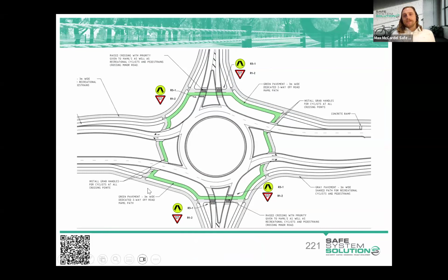So that's when we've got the single lane roundabouts. But when we're talking multi-lane, things get a bit trickier because it's very difficult to be able to provide that continuity for bike riders, basically. There are issues with providing the continuous crossing point because of sightline restrictions. And so unless you've got significant gaps in between the traffic lanes, you'd be hesitant to create those protected roundabouts where you've got multiple lanes.